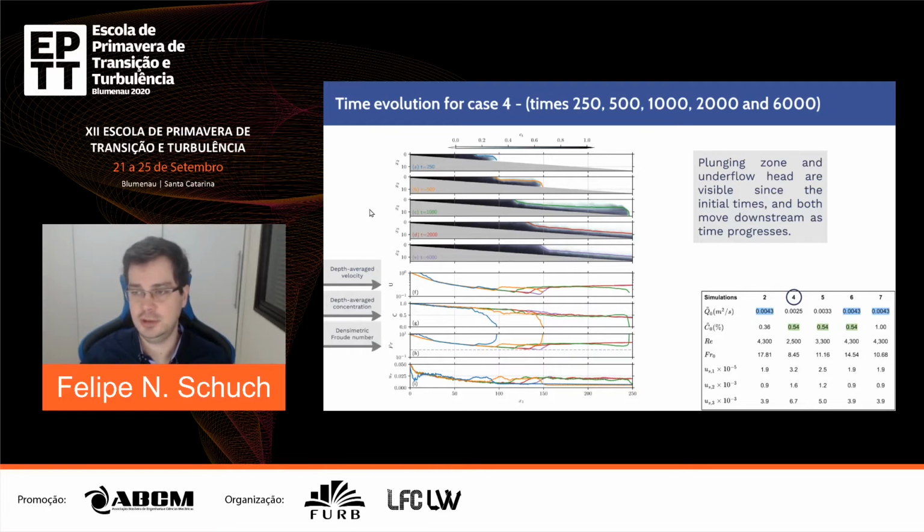We see the sediment Froude number as well. It's minimum at the plunge point. This value is around 0.45 here at the stable plunge position and around 1 here at the head of the submerged flow. And we can compute the bed shear velocity even though our model does not consider erosion or resuspension. We can compute it afterwards to see where it's more likely to happen.